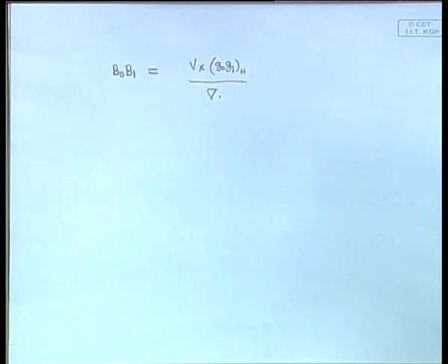So, what do we have here? We have a volume, which we call a wedge, shifting from one side to another, that is, from one point it is moved to another point in the whole ship. There is a shift in the B of the wedge itself, and because of this movement of the wedge there is a shift in the B of the ship itself.